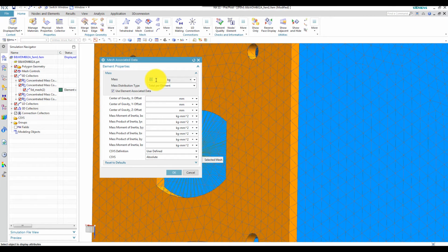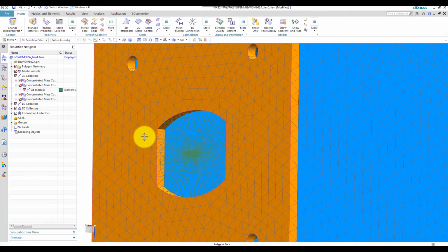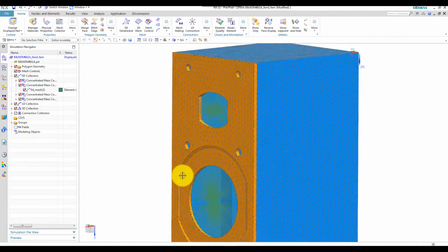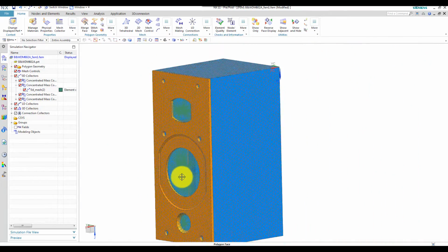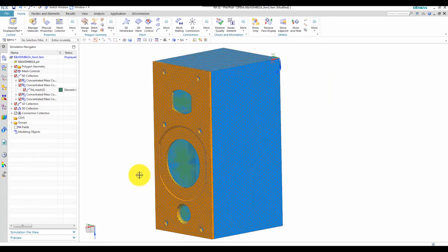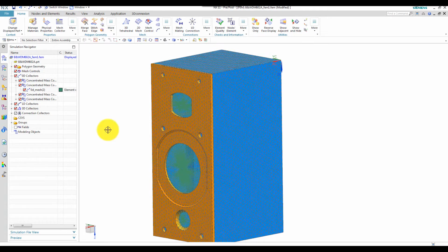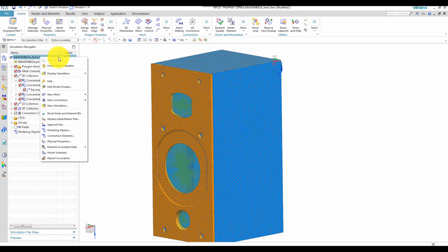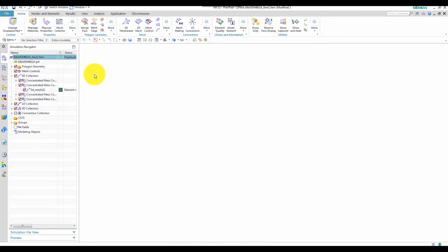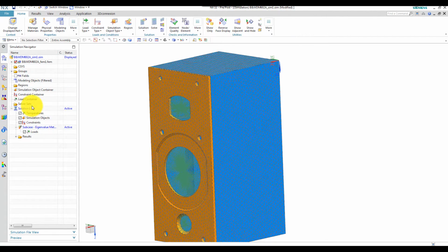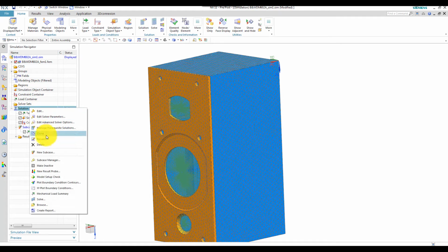Let's say that we can find one which is 0.3 kilos. There are 2 ways of increasing the eigenfrequencies: you can increase the stiffness or reduce the mass. Then we go to the solver, the sim file, and we run the simulation once more. Let's see what the results are.